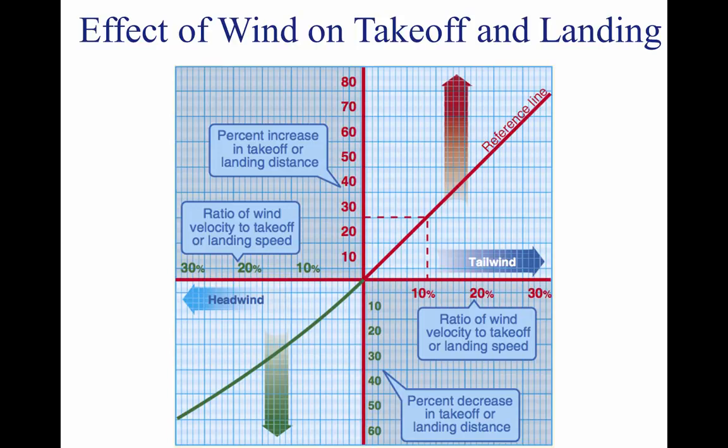An increase in density altitude can produce a twofold effect on takeoff performance: greater takeoff speed and decreased thrust and reduced net accelerating force. Proper accounting of pressure altitude and temperature is mandatory for accurate prediction of takeoff roll distance. The most critical conditions of takeoff performance are the result of some combination of high gross weight, altitude, temperature, and unfavorable wind.